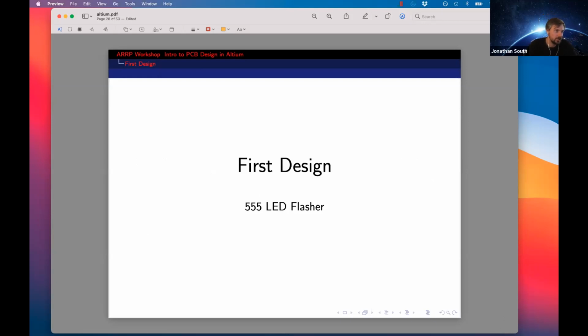Yeah, so an NC drill file. Yufan's got a question here. What's an NC drill file for? So it's used in conjunction with the Gerber file. Again, I'd recommend jumping onto a manufacturer's website to get the hard truth on this. But from what I understand, the NC drill file defines exactly where and what size the holes in our PCB need to be.